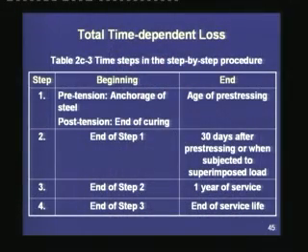That means in the first month the creep and shrinkage can be substantial, and hence we are evaluating the losses over the first 30 days, or if the time to imposing the load is larger than 30 days, then we may consider the period from the age of pre-stressing to the time when the member is subjected to the superimposed load.